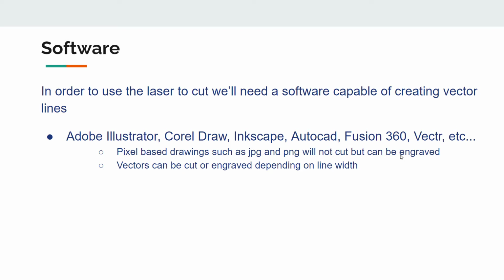So here's the important distinction you want to leave with. Pixel-based drawings such as JPEGs and PNGs, these can be engraved, but they cannot be cut. Vectors can either be cut or engraved.